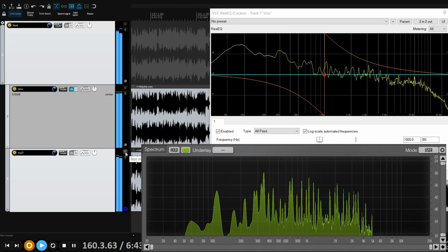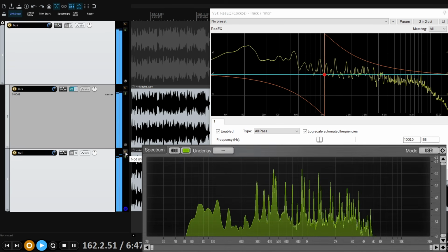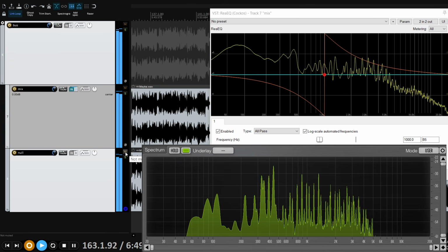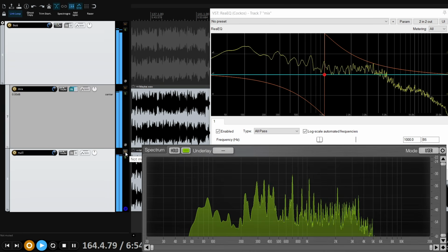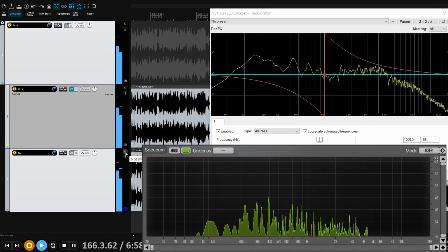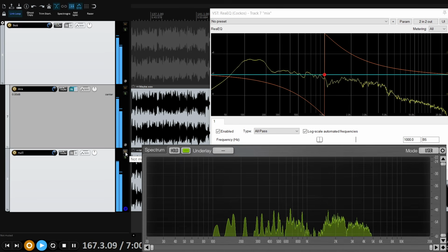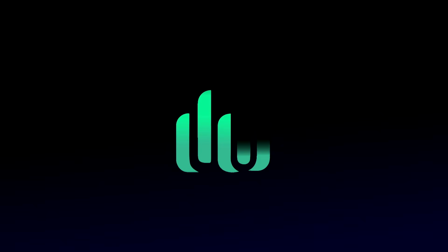The frequency that is flipped by 180 degrees by the all-pass filter no longer cancels out. In fact, it's back in phase with the inverted signal we're trying to null it against, so this frequency is actually boosted in level. The null test tells us this is a huge and significant difference, but our ears don't really care about it at all. The complexity of our hearing is another reason to use null tests.